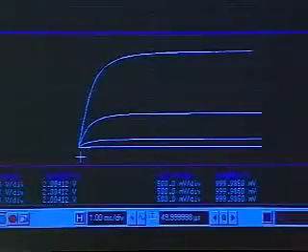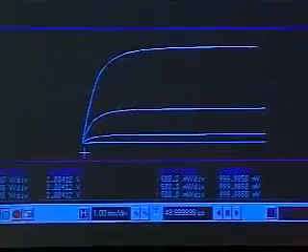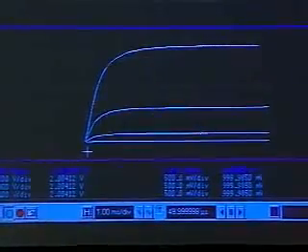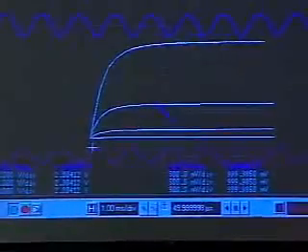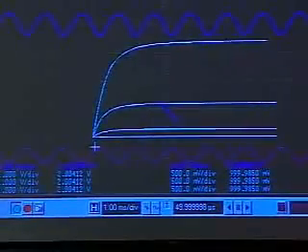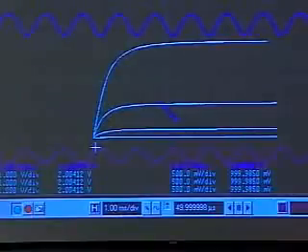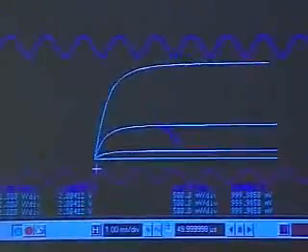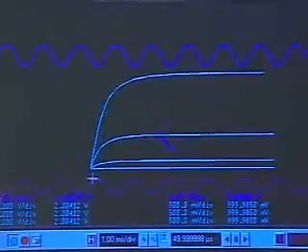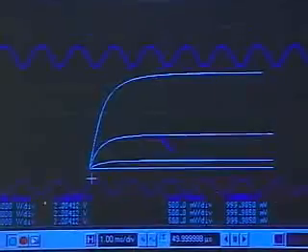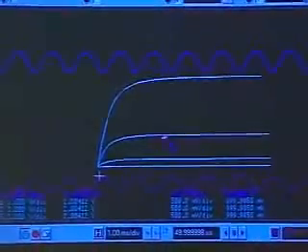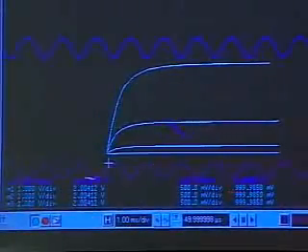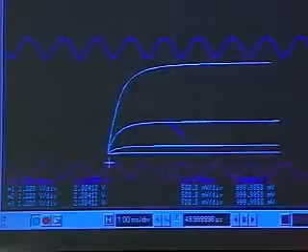Okay. So next what I'll do is show you some more fun stuff. Instead of having just a dot by having a DC voltage, let me apply an input sinusoid. If I apply an input sinusoid at some bias, then I should see an articulation of the corresponding region of the load line corresponding to the input. So as you can see here, the bottom line is my input, and this is my output. And notice that this is the region of the load line articulated when the input is of this magnitude.